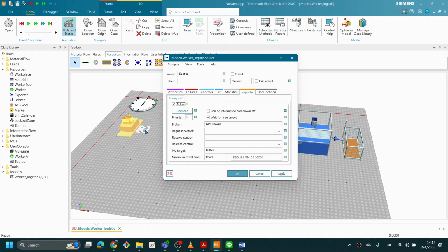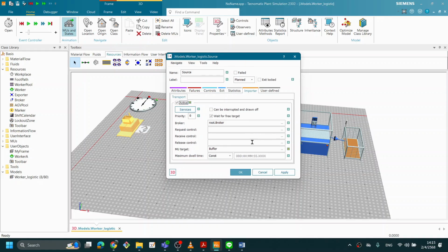The worker can wait for the sorter to deliver five workpieces. You need to set up the time for waiting in this location, in the workplace location, before the sorter is ready to give you five workpieces. Okay, set up about 1 second. So 1 second.